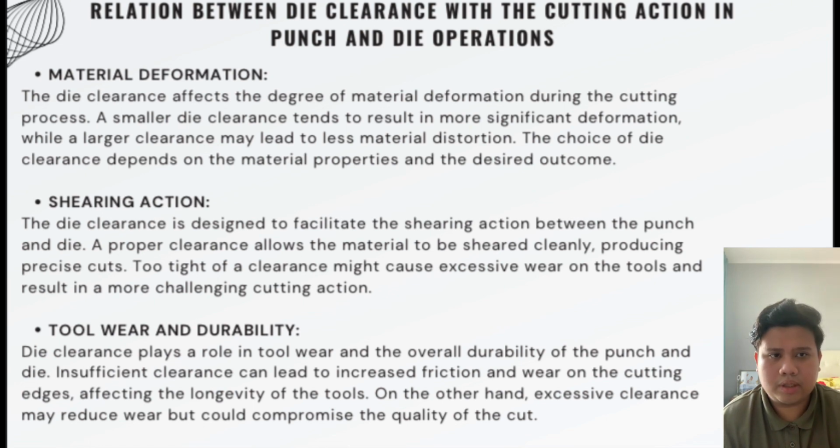Die clearance plays a role in tool wear and the overall durability of the punch and die. Insufficient clearance can lead to increased friction and wear on the cutting edge, affecting the longevity of the tools. On the other hand, excessive clearance may reduce wear but could compromise the quality of the cut.